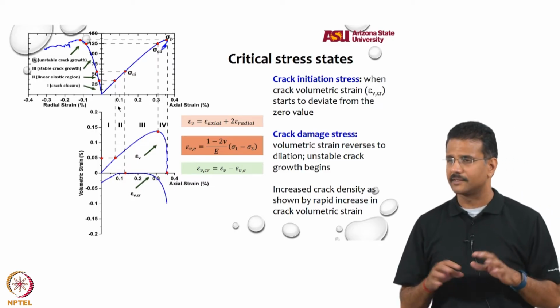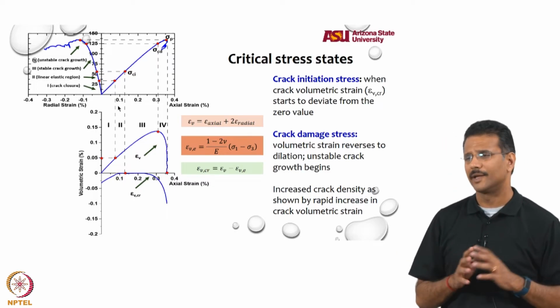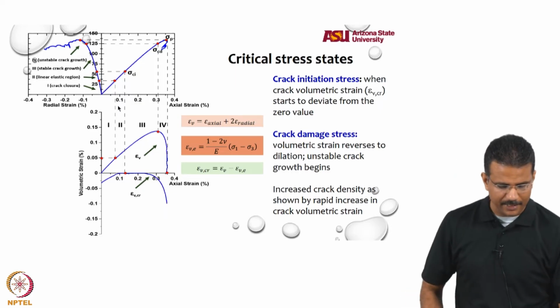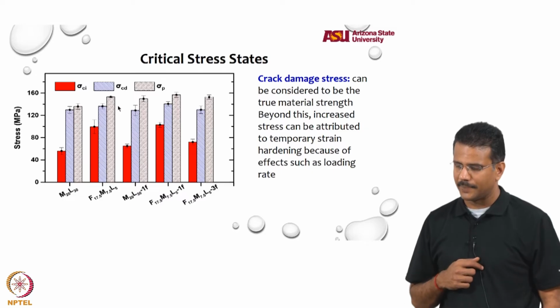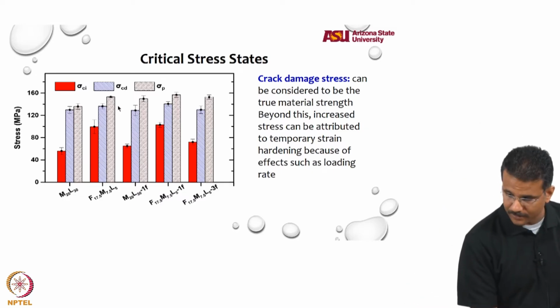Rapid increase in volumetric strains and such is a loading effect, so you do not want to consider that. Crack initiation and crack damage stresses are about 25% lower than peak stress. So, two different critical stress states.